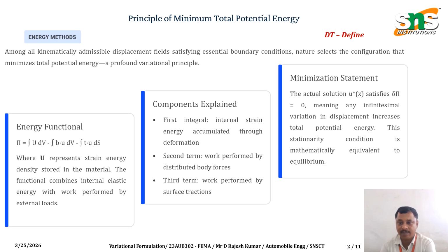The fundamental statement. Among all possible displacement fields that satisfy the essential boundary conditions, we call these kinematically admissible displacement fields, nature always selects the configuration that minimizes the total potential energy. Think about this for a moment. It always chooses the path of least energy.